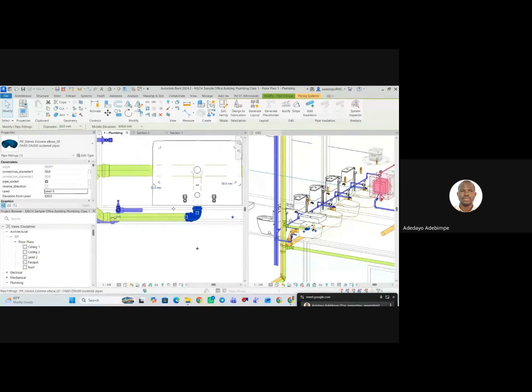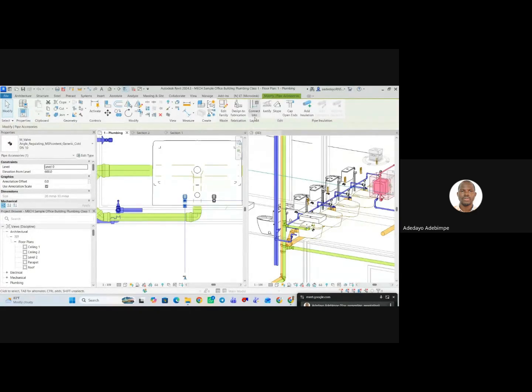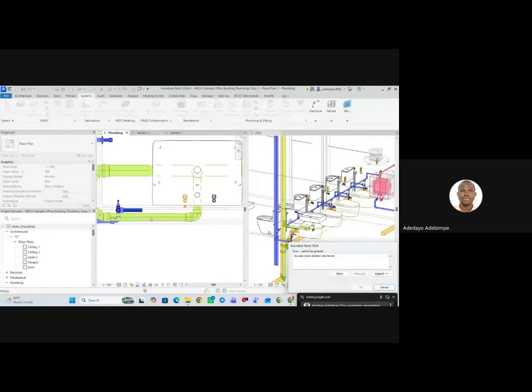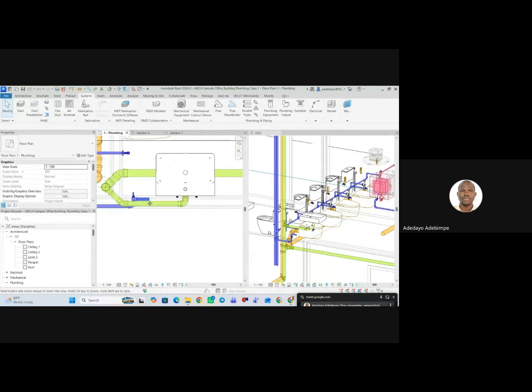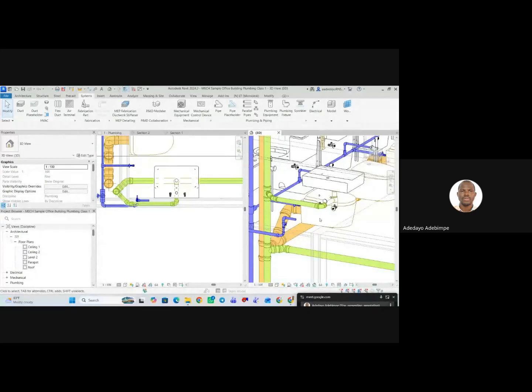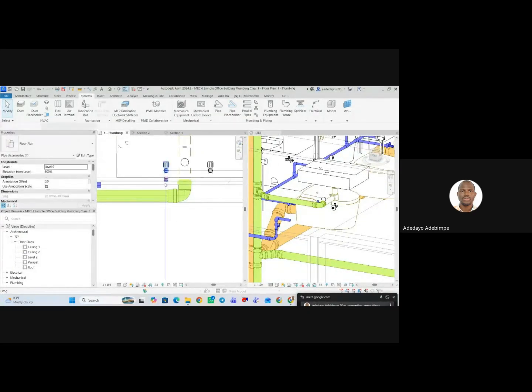So I'll right click on my angle valve again and do connect into 20 mm. I'll pick this. So there's not enough space. So how do I resolve this? Let me check my 3D view. So let me draw out a section of pipe from this angle valve.